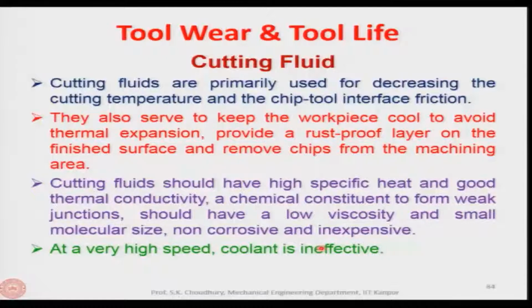Now, let us see the effect of the cutting fluid. Cutting fluids are primarily used for decreasing the cutting temperature and the chip tool interface friction. So, there are two functions of the cutting fluid: to decrease the temperature and to decrease the friction between the chip and the rake face of the tool. They also serve to keep the workpiece cool to avoid thermal expansion, provide a rust proof layer on the finished surface and remove chips from the machining area. These are known.